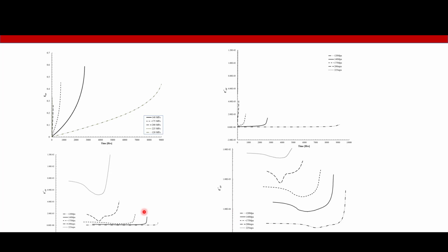Okay, and then this is double log. This is log only on the x-axis, on the time axis, and then you make it a log plot, and you will see that it becomes very clear. Also the trend, and you see that there is no steady state creep here. Okay, so there is no plateau. The slope constantly changes.